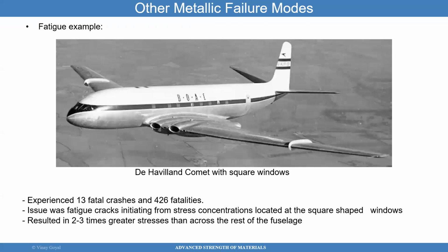Here's an example of fatigue failure where the Comet aircraft had a situation where the corners of that fuselage cracked and then propagated. You may have heard of the recent 3 or 4 incidents with Southwest Airlines, where parts of the fuselage came off. In Yuma, Arizona, for example, a person passed away because a blade came apart and it hit the window and it sucked the passenger out.